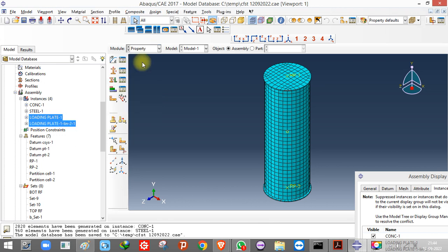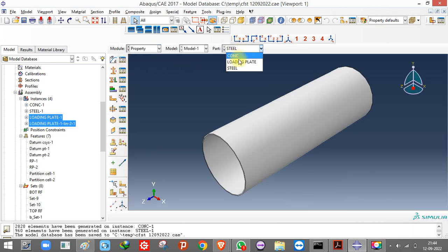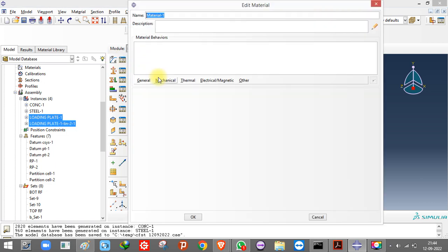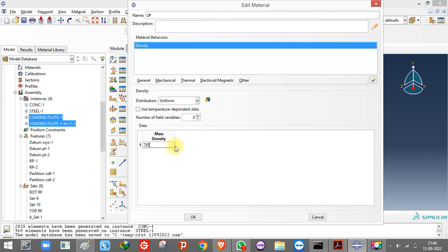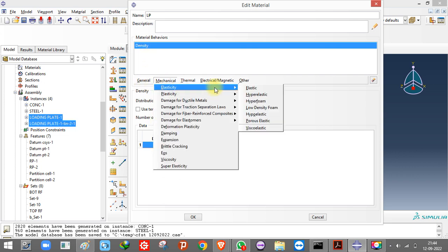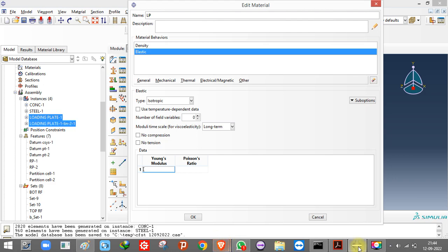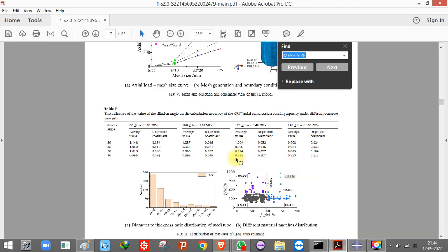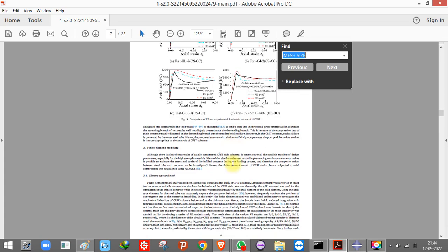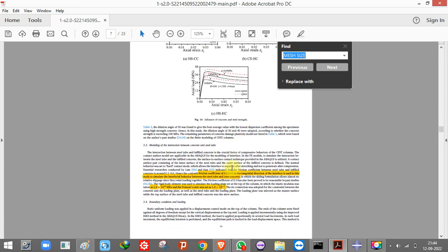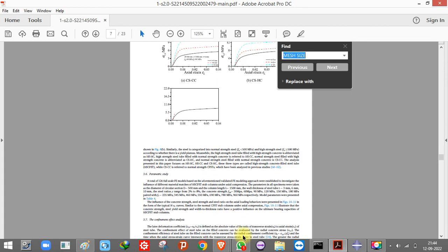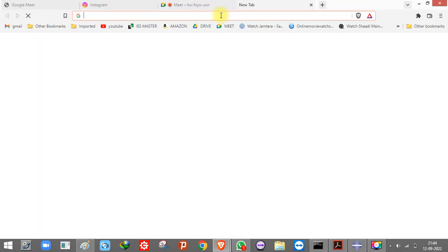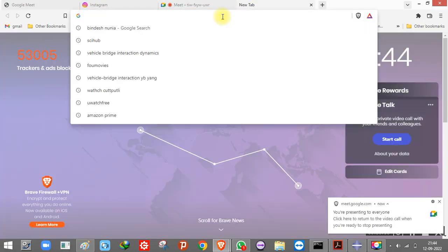Everything is done. I'll just have to assign the property. So first I'll create the property for loading plate. LP. Density is, let's say, 7850, not required, but still I'll give. Modulus of elasticity they have given over here. So what are the unit consistency that we have to maintain for the properties? Properties, as I have said, I am working in mm. So wherever you are working, entering the properties, always you have to enter those in mm.